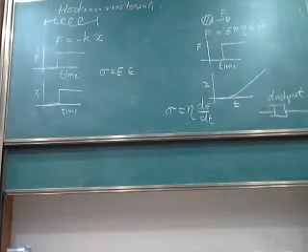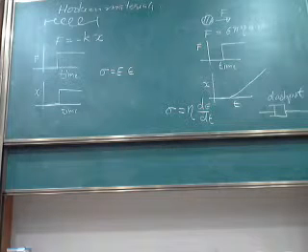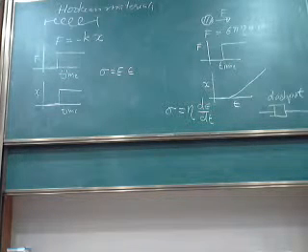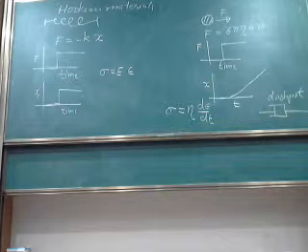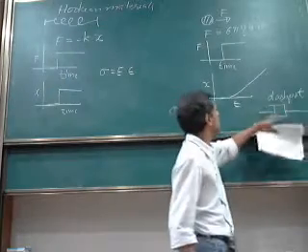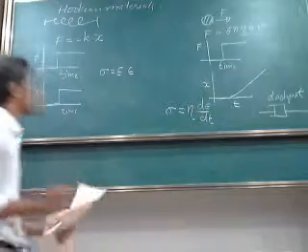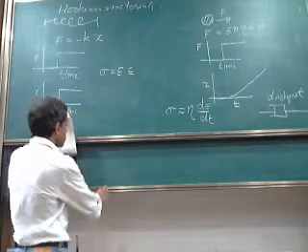For example, if you take a syringe and fill it with some viscous fluid, and if you apply a constant force, then the fluid comes out at some rate. So it limits how fast I can push, at what rate the piston is being moved. That's why it's usually represented by a cylinder and a piston. So it's a purely viscous element.